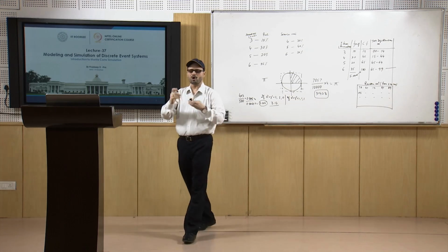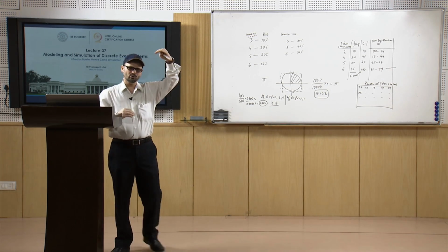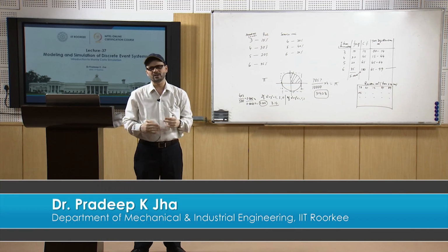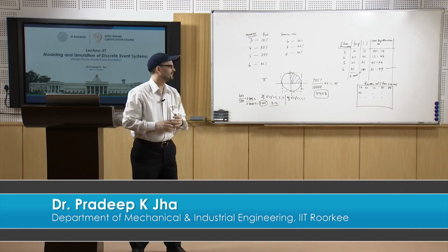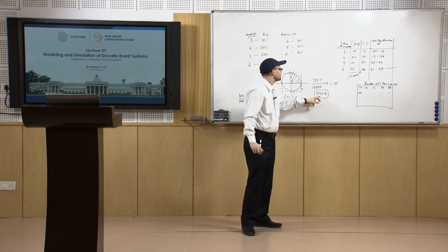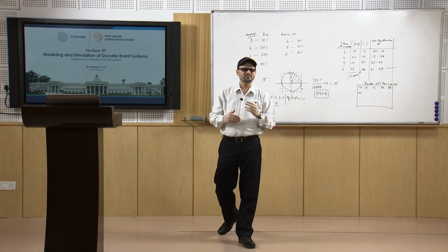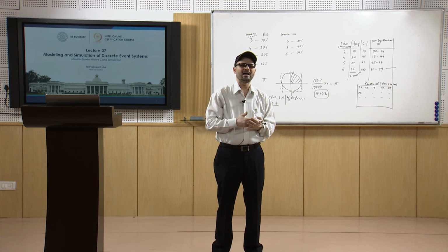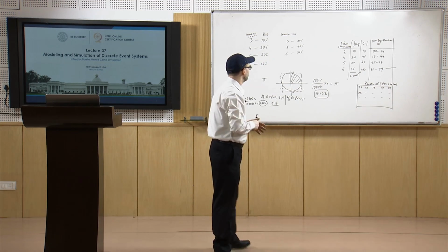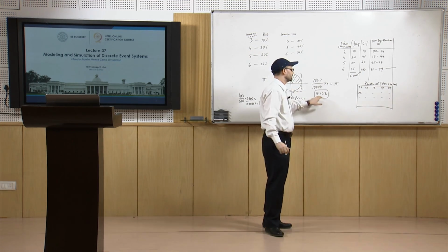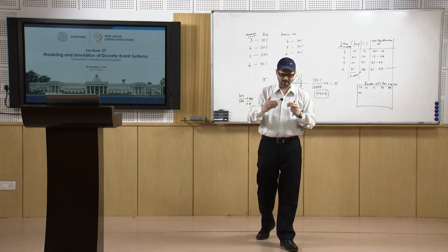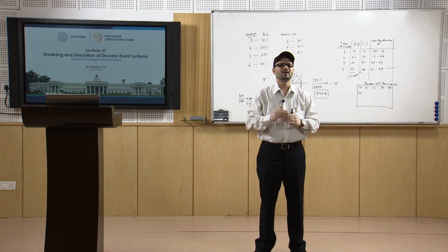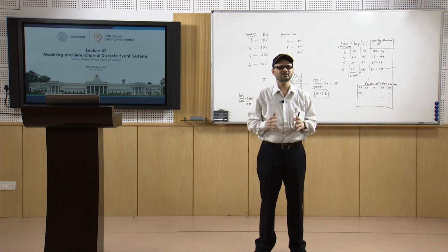As you go on increasing the random number streams from 100 or 500 to 10,000 and more, it is coming closer and closer. So, this is the concept of using random numbers. If you do it for a large number of iterations, you will see the average values coming closer to the expected value of the parameter, and this way, using random numbers, we do the stochastic simulation.